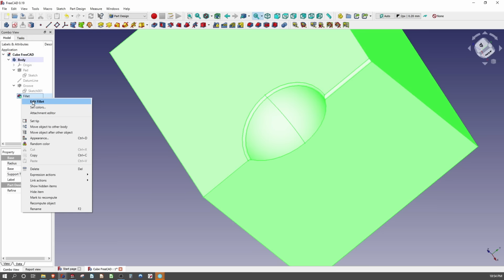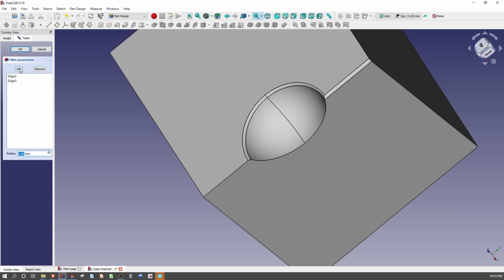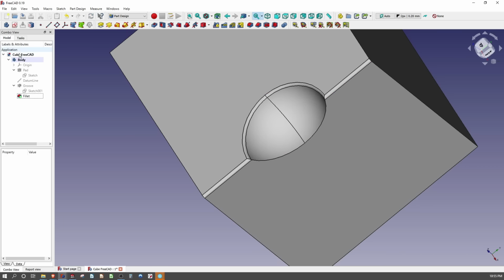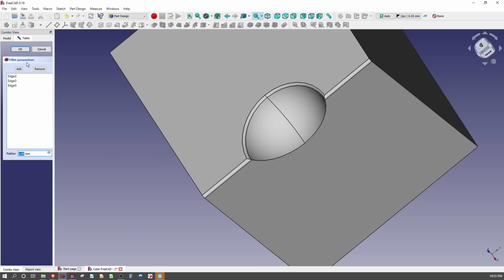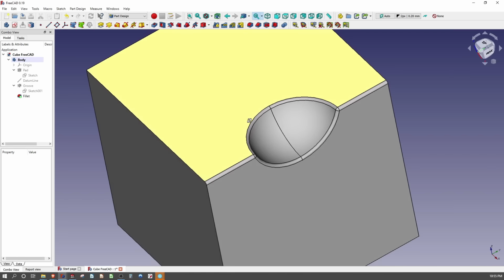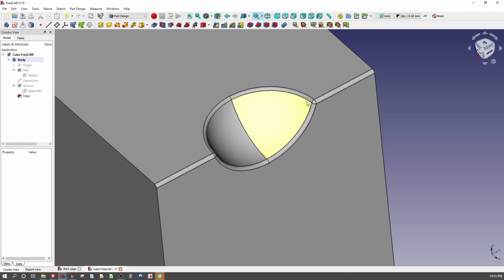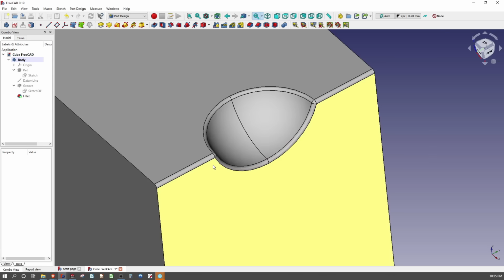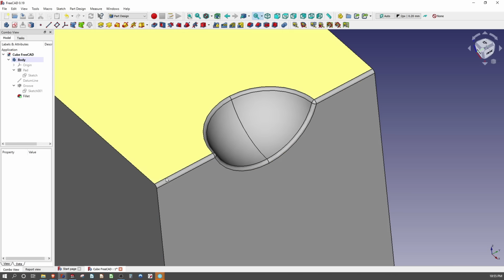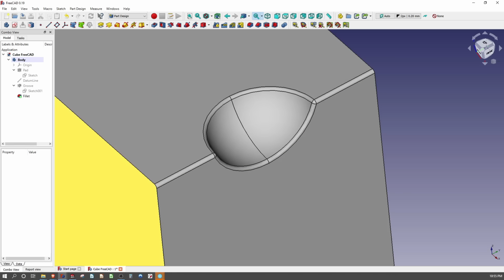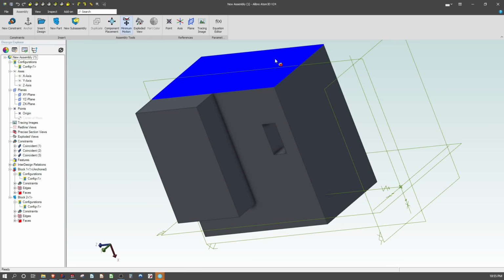Now, to be fair, I can edit my fillet and simply add the edges in here, right? But in certain filleting situations, there isn't always a way around it like this, right? Sometimes you'll get failed to create fillet no matter how you go about it. It just fails to create a fillet. And it's very understandable because fillets are very hard to create sometimes.